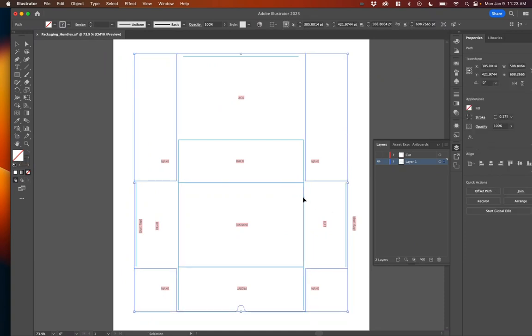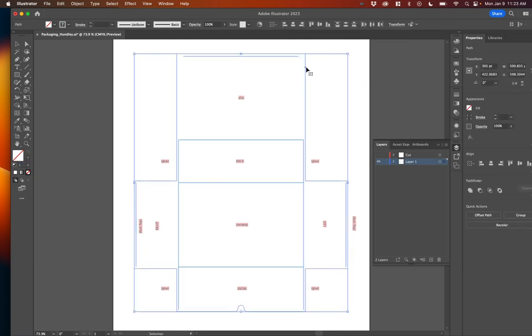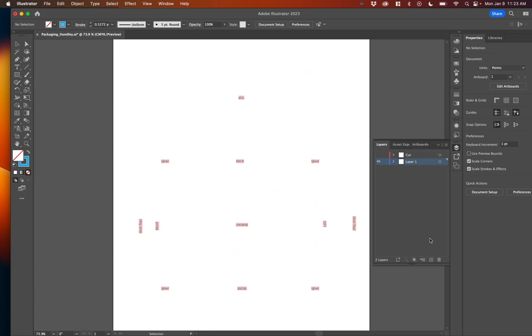I'm going to also pick up those blue lines. You know what, I think an easier way to do it is select all the blue lines, hold shift. Now I have all the lines that I need. These are all the bold lines and everything. Group those, cut those, and make a new layer that's called bold. Paste in front.